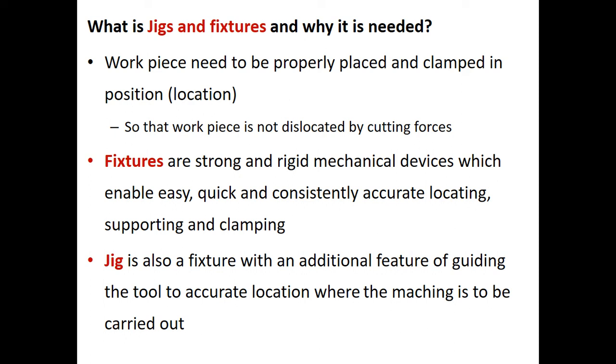So the differentiation between these types of workholding devices, please note the terminologies I am using while you are hearing the lecture, is in their relation to the cutting tool. So the jig guides the cutting tool, a fixture references the cutting tool. Maybe that would be a nice interpretation, I will say.